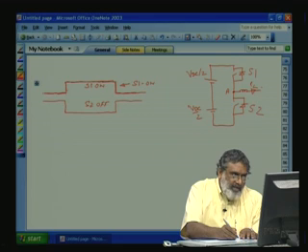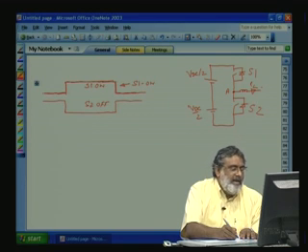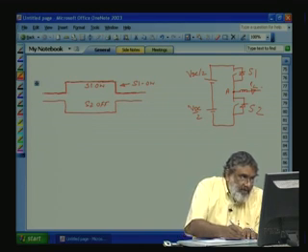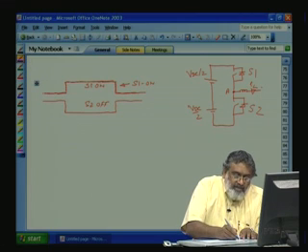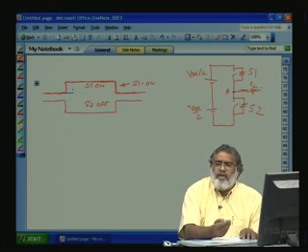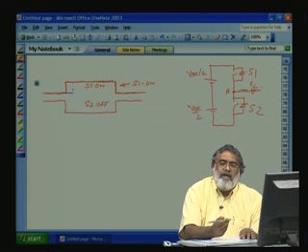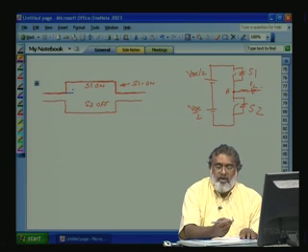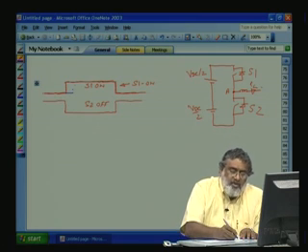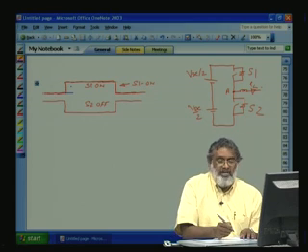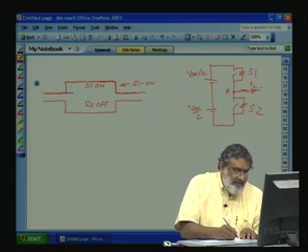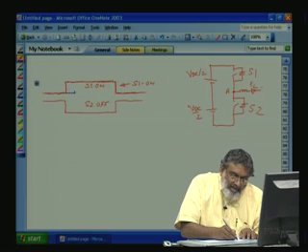So, instead of turning on here, we will give a delay, let us say a delay of TD. It depends on the device. Let us say for thyristors, converter grade thyristors require a large time, 30 to 40 microseconds. But for IGBTs or power transistors, you will get a few microseconds. Still, with PWM switching, it can affect the output, so we will study the effect of that. We will give a delay and then turn on. This is the delay we are giving.